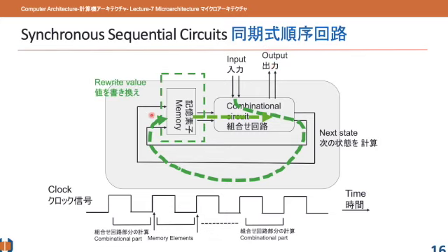In the next cycle, it goes here, it comes from the input, and we get the output. So in every cycle, it changes the value of the memory element. It comes from here and overwrites the memory, and then goes to here to execute the combinational part for the next state. So with time, in every clock, it's doing the same thing repeatedly. And this is the behavior of a sequential circuit, and hence the behavior of a microprocessor.